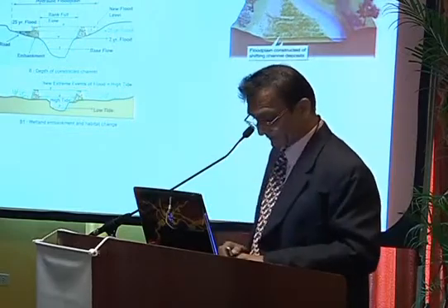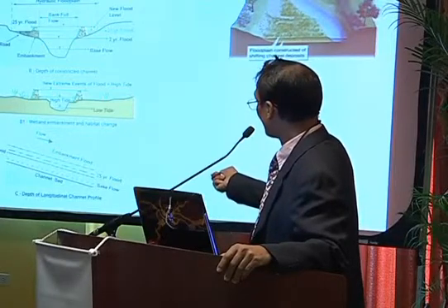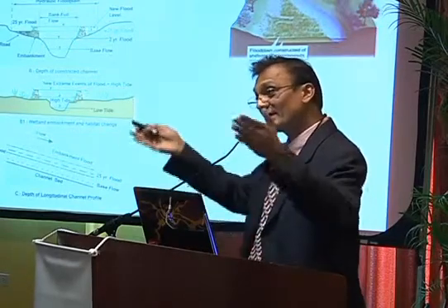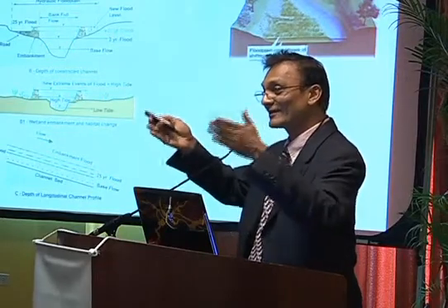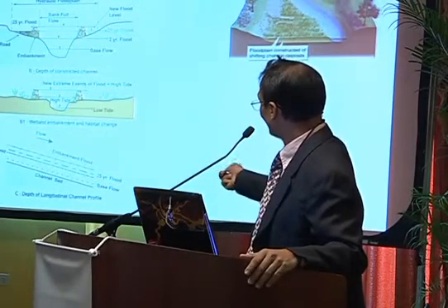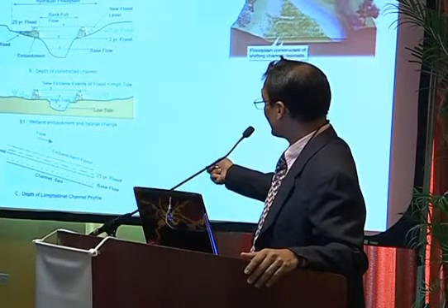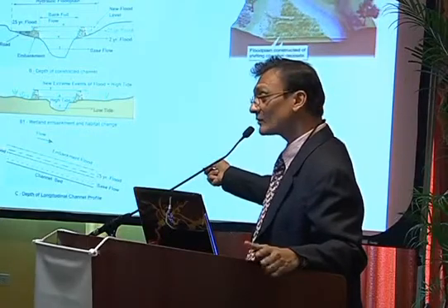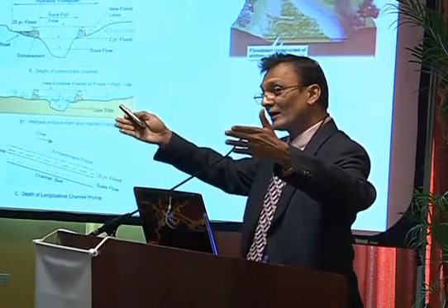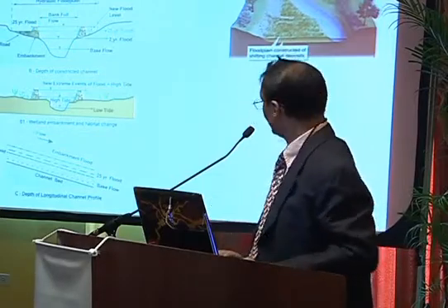So to summarize, if this is a channel bed, the base flow and the 2-year flood return period are not interfered with, although we do sometimes fill in that river section and build retaining walls, reducing the capacity even at the 2-year return period. So let's assume we don't do that. So we have the 25-year flood here actually being higher in the embanked area. We have backwater effect here causing flooding upstream likely, and then the floodwaters have to go through quickly through the embanked area, so you aggravate flooding downstream and possible erosion.